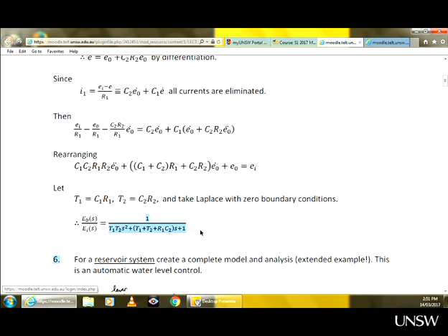So it is a second order transfer function. That means 2 time constants, in theory at least. But if we can factorize this polynomial, then definitely we'll have 2 time constants. And the steady-state gain will be 1. How do we know? Well, first of all, this is a non-dimensional form of the transfer function. That means steady-state gain, or DC gain, can be read right from the numerator, which is 1.